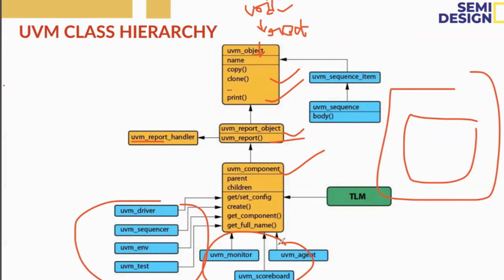So it will extend the classes from the UVM classes because the logic is already predefined in the library. If you take the report mechanism, the logic is already predefined in its methods and verbosity levels. If you take objects, the functionality and class definition are already there in the copy, clone, and print methods. We can just use the methods.